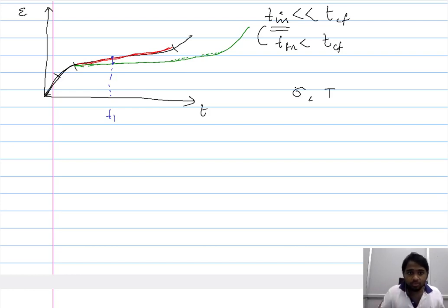If you could recollect, we spent some time studying the transient creep in addition to the steady state creep, because the amount of strain that is introduced during the life of the material at high temperature is largely due to the instantaneous and transient creep. So therefore, the strain is introduced during the transient creep, the stage that precedes the steady state creep.